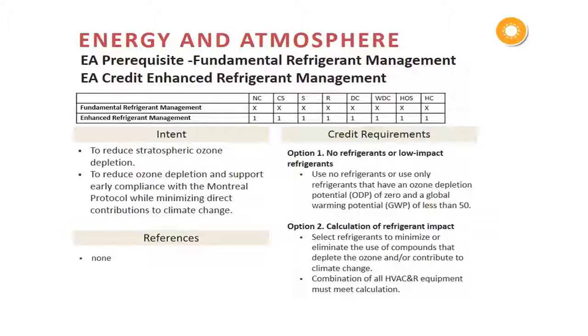So it looks at refrigerant type. So is it a CFC12? Is it an HFC? What have you in terms of refrigerant type? It also looks at the charge of refrigerant in each piece of equipment. So, and by charge, I mean how many pounds of refrigerant are in that system. Finally, it looks at the cooling capacity of the system. So a system that provides more cooling is given a little more flexibility in how much refrigerant or what type of refrigerants they're using.